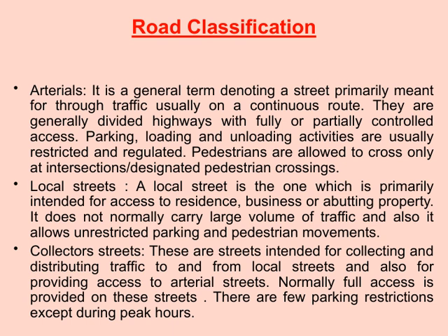Lastly, we have collector streets. These roads serve as the connectors between local streets and arterials. Their main purpose is to collect traffic from neighborhoods and distribute it to the larger arterial roads. They also provide access to local streets, so full access is typically available here.